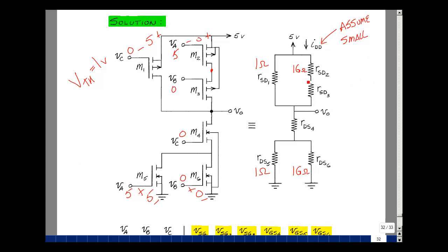Now what about this voltage? Now if I have a small current going through here, I can't figure out this voltage, but this is in parallel with everything, so that small current is also going down this other path. That makes this node voltage here about 5 volts. That makes this about 5 volts also. This minus this would be 5 volts. That would make this a low resistance. Likewise over here, having a low resistance back to ground, this is going to be sitting at something close to 0 volts. 0 minus 0 is 0, 1 gigaohm. Do I have a small current? Well, I have 1 gigaohm in series with this, in series with this. Something when I divide that into 5 volts in nanoamps, so I have a small current.